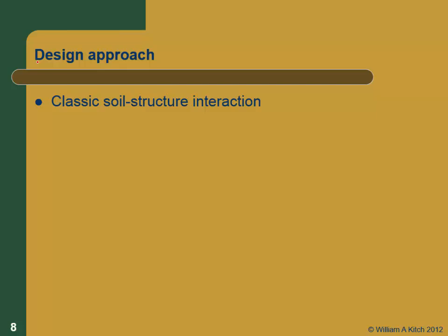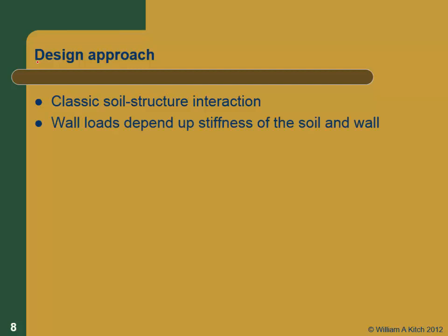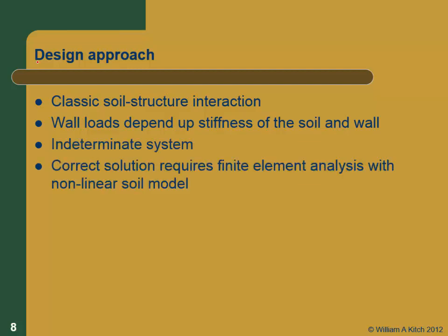The problem is really a soil structure interaction problem, and it's an indeterminate structure. We really need to know the stiffness of the soil and the displacement of the soil to calculate the problem, because we've got more unknowns than we have equations to solve without including stiffness. So the wall loads are dependent on the stiffness of both the soil and the wall. It's an indeterminate system, as we just said.